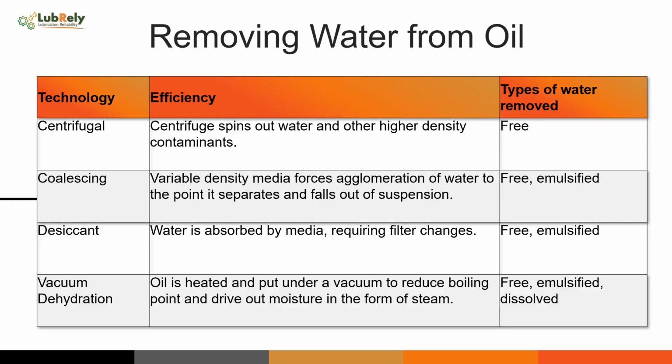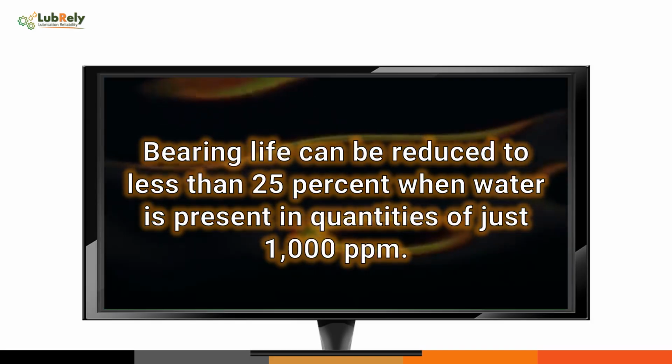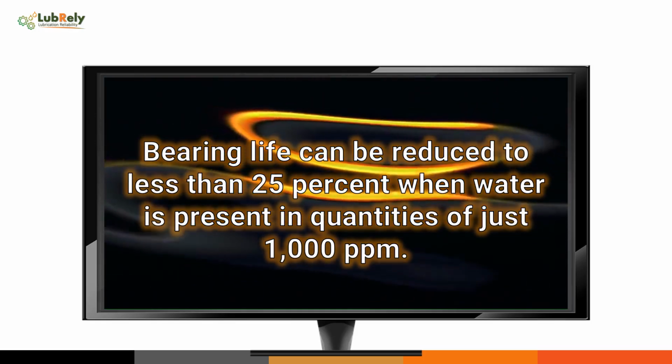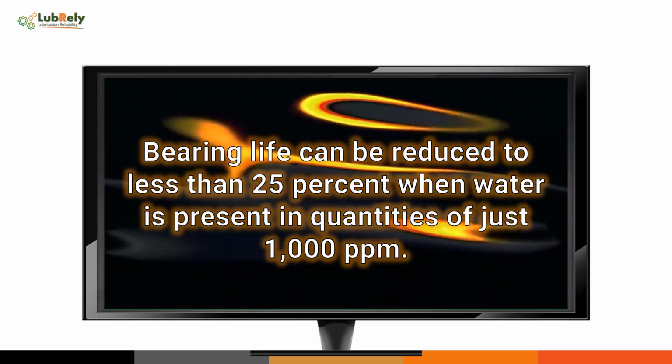Basic measures to address water ingression include the use of desiccant breathers, improved seal technology, and training maintenance personnel to avoid direct contact with water on shaft seals and breathers. Water is a major cause of lubricant failure, component failure, and poor machine reliability.